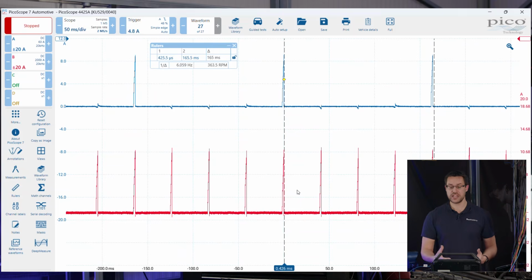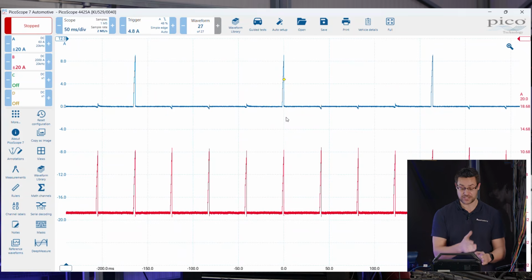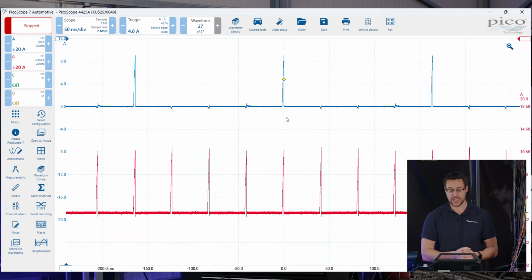So now we're starting to see how we can utilise, especially with current loops, triggers for sequential firing actuators like injectors and ignition coils. They are helping us stabilise on the screen whilst also giving us something to actually reference when we're doing our firing order sequence, for example. And we're now also seeing how timebase can change how much of the signal we see compared to how much we don't.